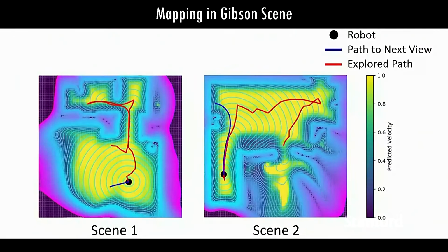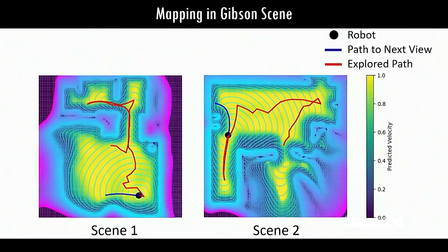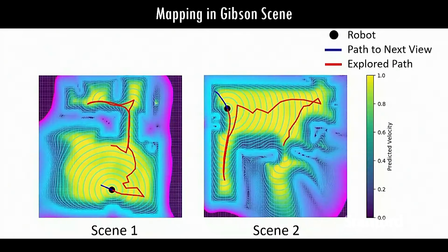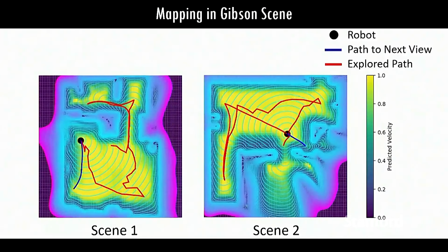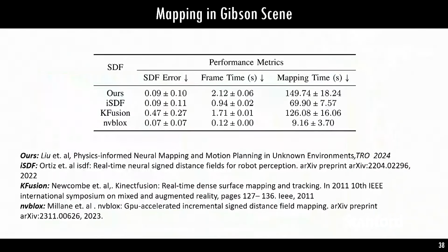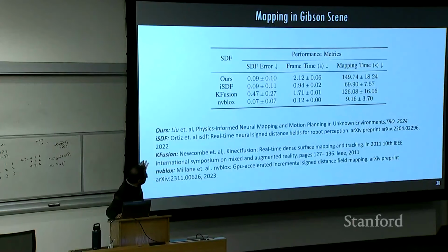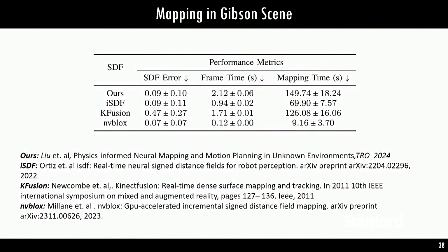And then once you have this map, you don't need any motion planning tool. Just follow the gradient of this map. It incorporates that geometrical representation that helps the robot navigate the environment. In this paper, the mapping time was twice that of standard mapping like occupancy maps, but with our latest model, we were able to reduce this time by about 40%.